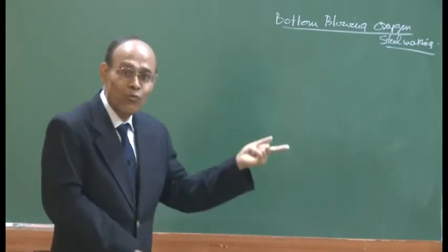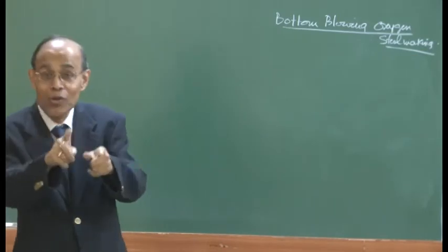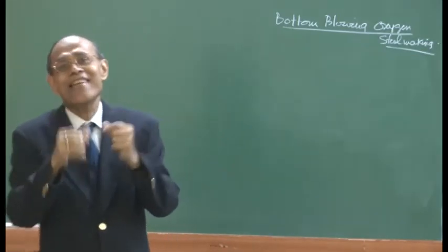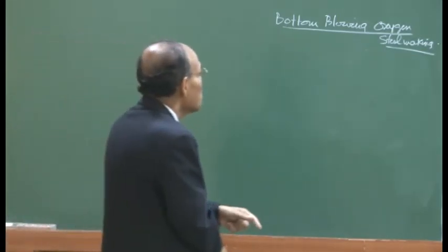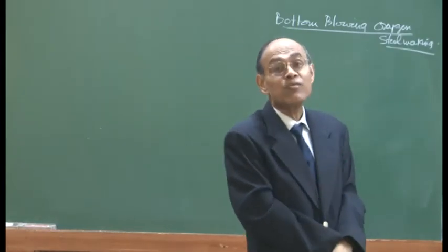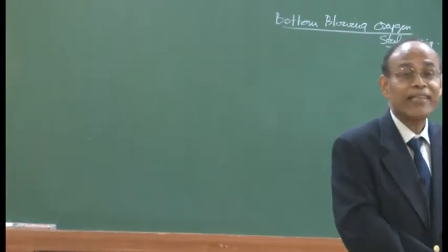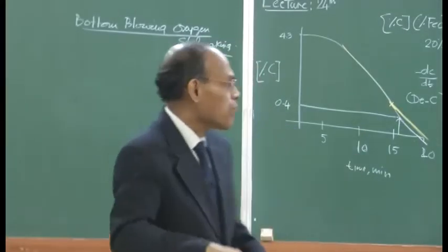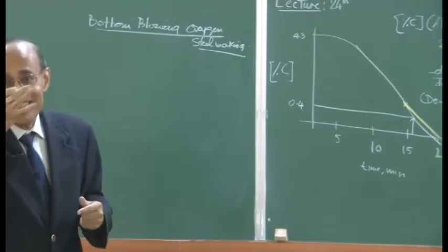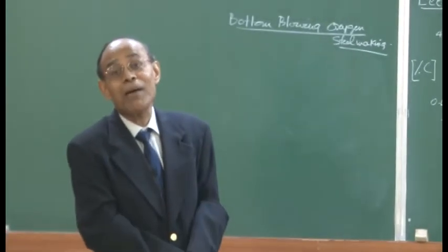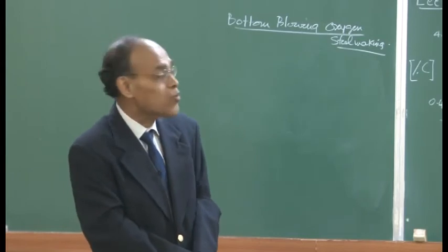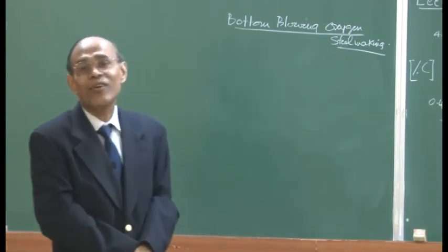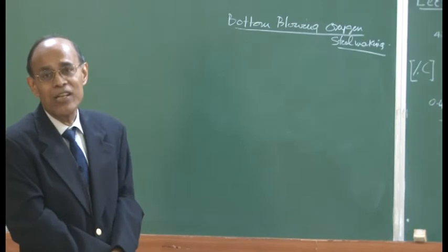In this case we want to do stirring, but at the same time we want to supply oxygen also, because oxygen is a reactant. But in other cases we will see that we may just want to do stirring. In that case I do not want to inject a gas which will react with the melt, I do not wish to contaminate the melt. So, subsequent to steel making, all the stirring processes will use, for example, argon as the gas to stir molten metal, because argon does not contaminate; even nitrogen will contaminate steel to a certain extent.